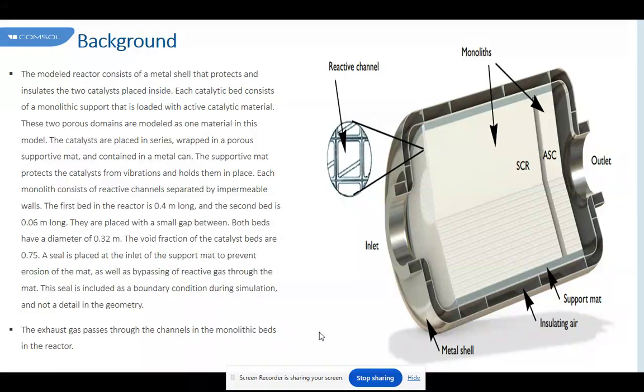Nishizawa and his colleagues in 1989 found that the conversion efficiency of the metallic converter is better than that of a ceramic converter of equal cell density. In contrast, Jasper and his colleagues in 1991 reached the opposite conclusion, while Pelters, Graf and his colleagues in 1996 concluded that the type of substrate doesn't significantly affect the conversion efficiency of the converter.